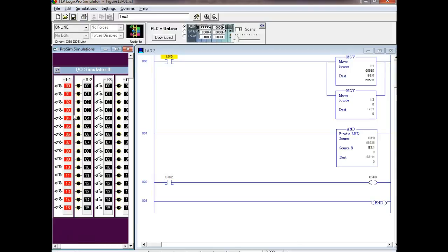So what I'm doing is I'm moving 2 numbers into my 2 registers. I'm adding B0 and B1. And right now I'm checking to see if bit 6 was set. What I would do is this right here would be my mask. So bit 6 is not set, or not 1, and what's my AND giving me back? 0. And now it is set, right? That makes sense.